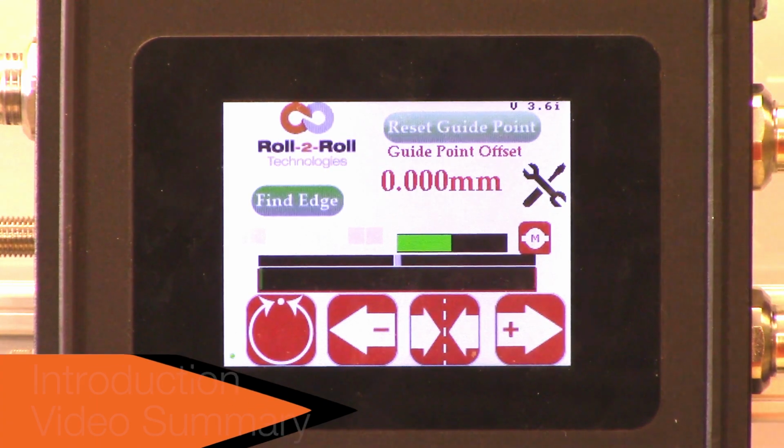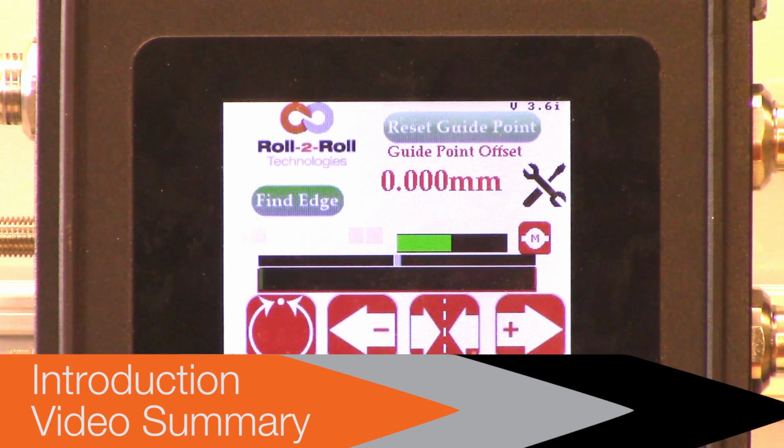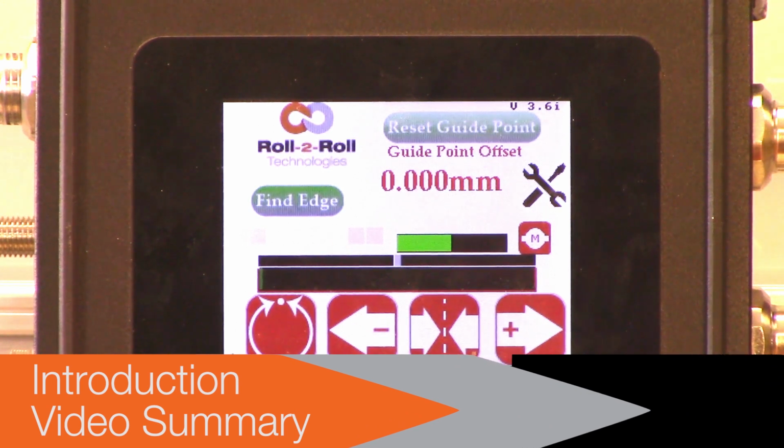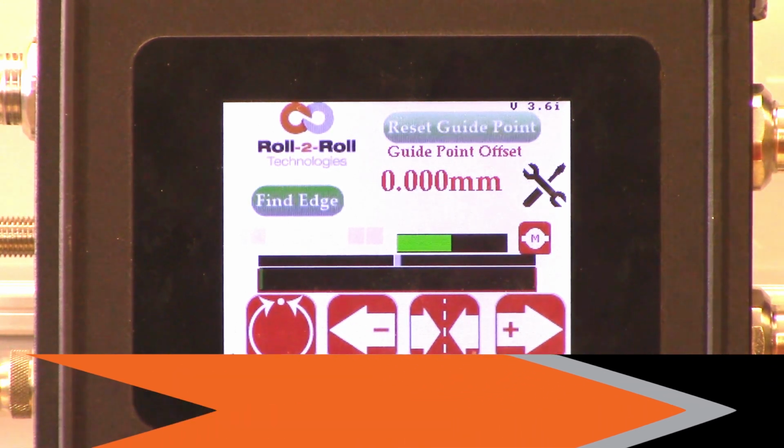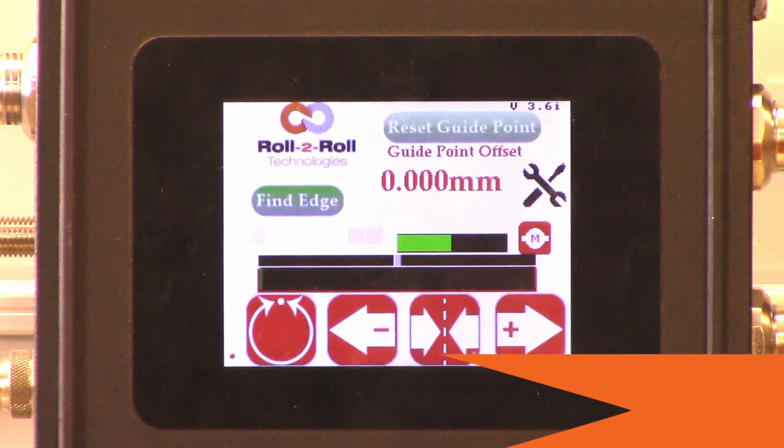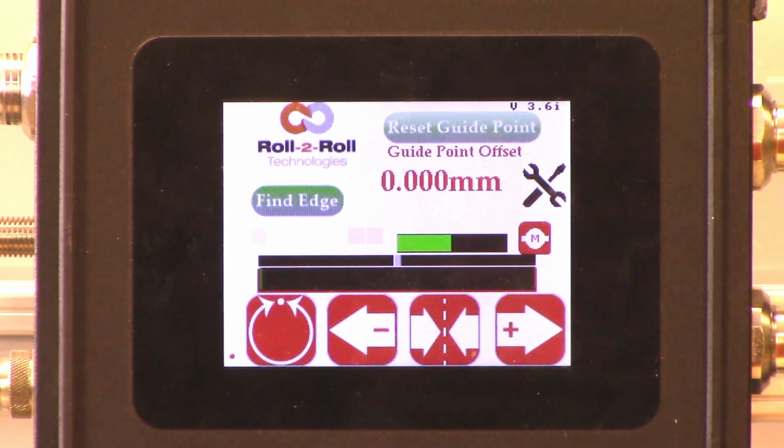Hello everyone. In this video we're going to look at how we can configure our SCU5 controller with a PROFINET industrial Ethernet protocol on it with a PROFINET controller. We don't have a PROFINET controller here, but we're going to use a PROFINET master simulator to show how we can add our SCU5 controller to a PROFINET controller using the GSDML file.